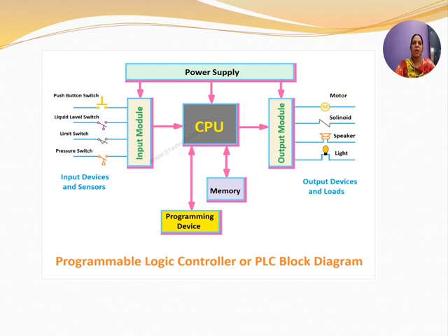This is where a PLC comes into the picture, which doesn't require any additional wiring and hardware to make the change. Rather, it requires a simple change in the code, that is, programming the PLC to turn on the light 30 seconds after the switch is turned on. By using a PLC, it is easy to incorporate multiple inputs and outputs.